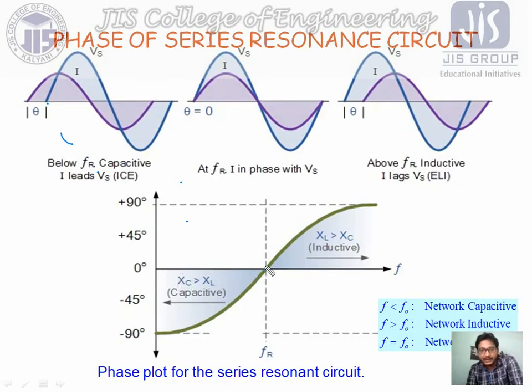similarly at the resonance point, the capacitor and inductor will have no effect. So here the circuit will have only the resistive effect. And we know the power factor, that is cos phi. Cos phi is equal to R divided by Z, and in series resonance condition, Z is equal to R. So at resonance, cos phi will be R by R, which is 1, right? So unity. So at resonance it will be unity.